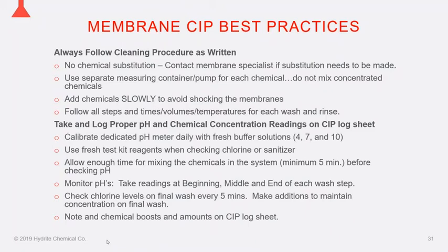You could take it from the concentrate line, you could take it out of a permeate sample port, doesn't matter. But an RO and a nano, think about what you've learned about ROs and nanos. What do they pass through their membranes? They pass just water for the most part. That's what they're supposed to if they're in good condition, right?